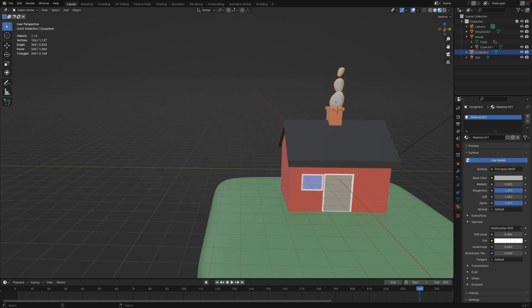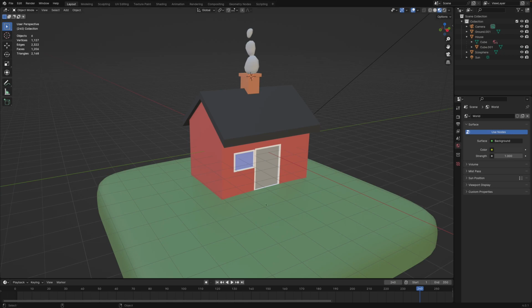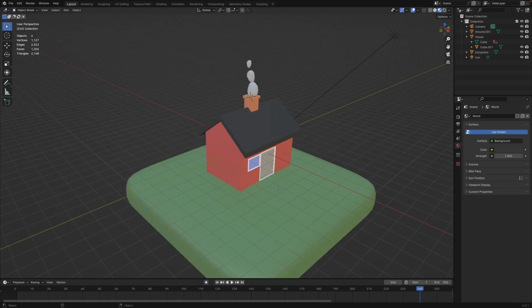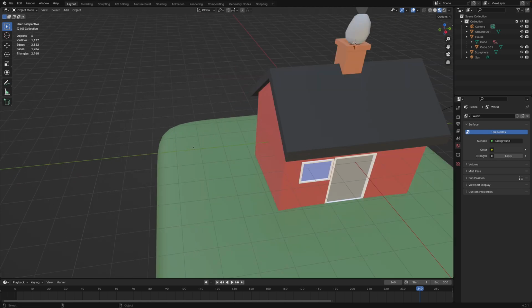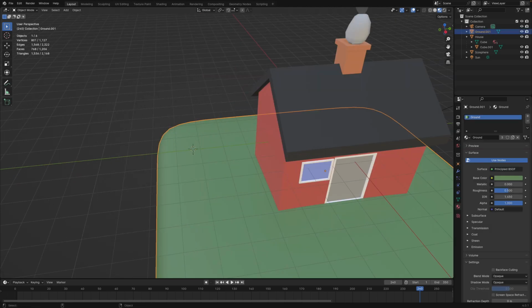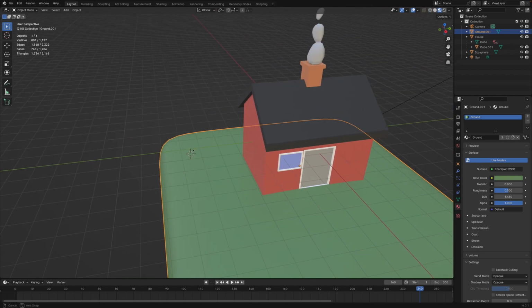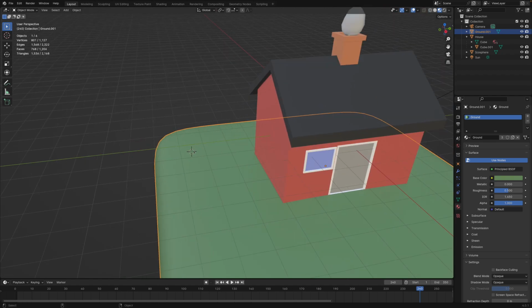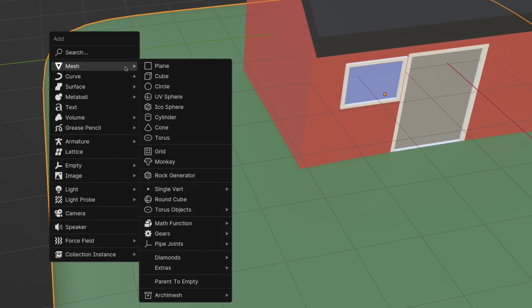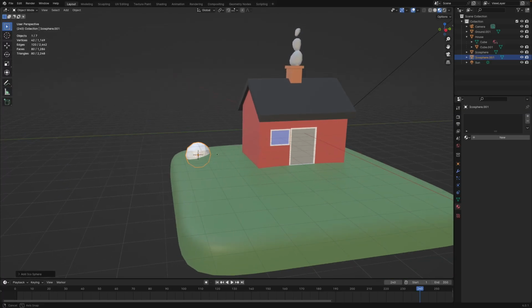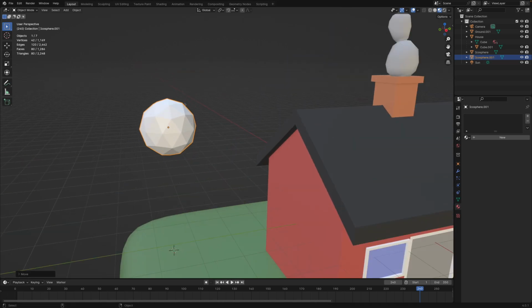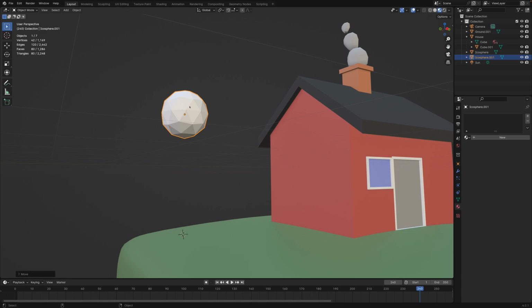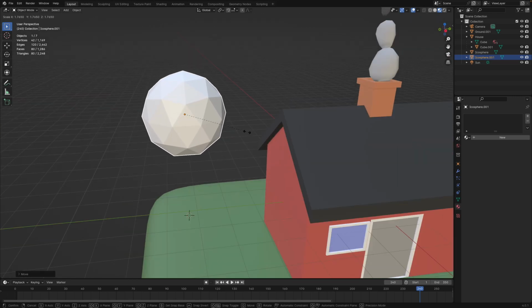Our scene still looks a bit empty, so let's add a tree. I will hover over here and Shift right click to change the 3D cursor. Shift A to add one more icosphere. Let's move it up. G Z, and this will be a 3. S to scale.